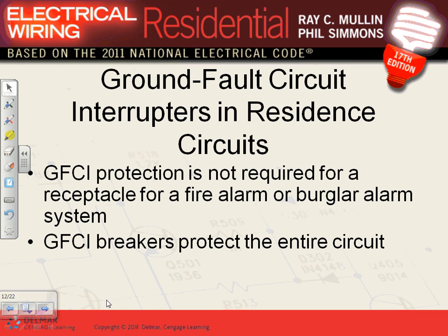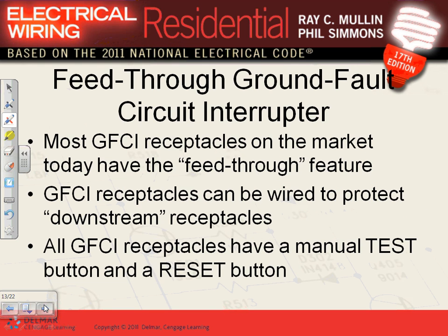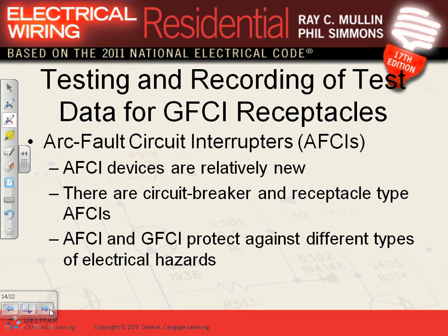Okay, required for... this is the exception that I told you guys. Exception for security system, burglary alarm system. If you have one receptacle in the basement dedicated for the burglary alarm system, it doesn't have to be on GFCI. You can meet the code by circuit breakers or GFCI, like you said. Feed-through and test for GFCIs. A couple of pictures I'll show you later on.